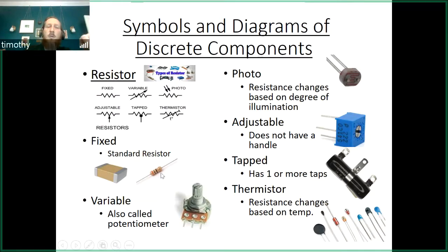This is a through-hole resistor with stripes on it to give color coding. You would put these leads through holes in your PCB and then solder fill those holes. Variable resistor. This is also called a potentiometer. Now, a variable resistor has this very sturdy looking handle on it. This is made for user input. It's made for a user to take this handle, turn it up, turn it down, and it is designed and built for that repetitive input motion.